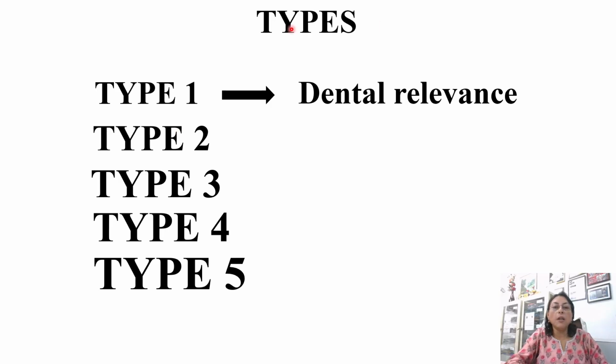Type 1 is called the normal Portland cement and is a general purpose cement suitable for all uses when the special properties of the other types of cements are not required. Type 1 Portland cement is generally more available than the other types of cement. For example, type 1, which is the ordinary Portland cement, is typically used in assorted construction applications.